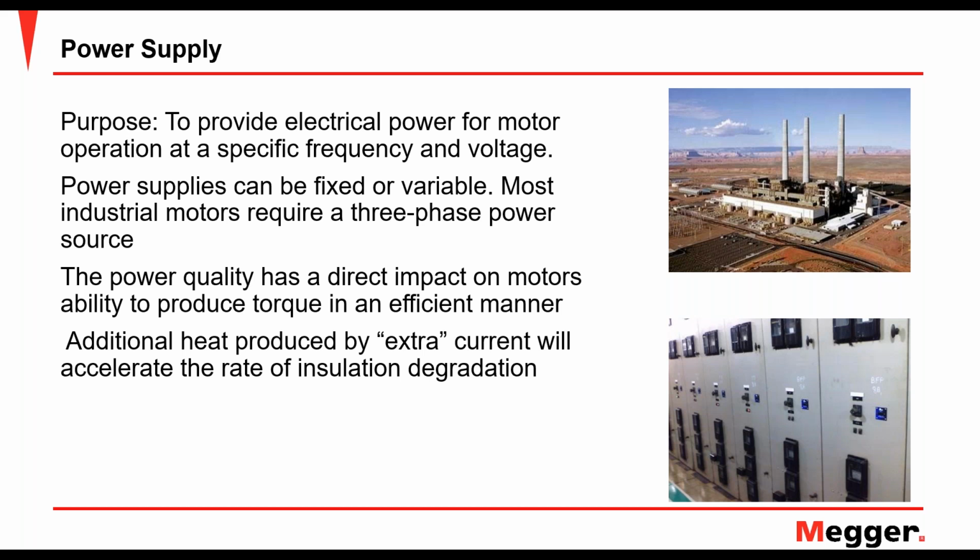If our power supply is bad or weak, then we're going to have extra current being drawn by that motor, which causes heat in the motor and makes the insulation degrade faster. So we are concerned about what kind of power we're giving this motor.